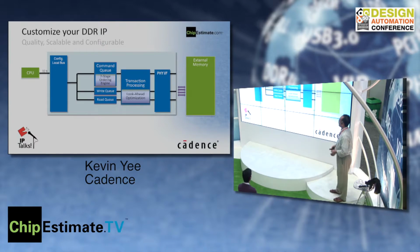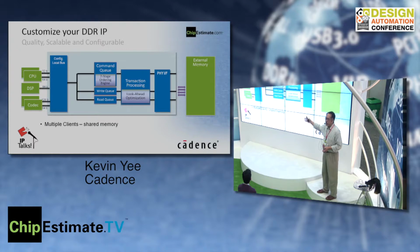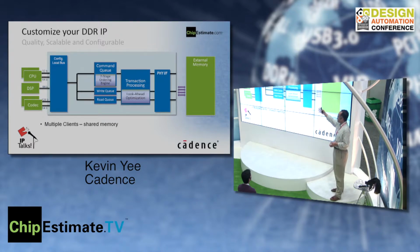We give you a lot of configuration. So the beauty of a memory controller is a lot of times you're going to connect to multiple CPUs or multiple controllers. You want to control the same memory. So we give support for multiple clients, whether you have multiple CPUs or codecs or DSPs that need access to that memory. We can support multiple CPUs or clients, but we can also support different bandwidths on that, whether it's going to be 32 bits, 64 bits, 128 bits.